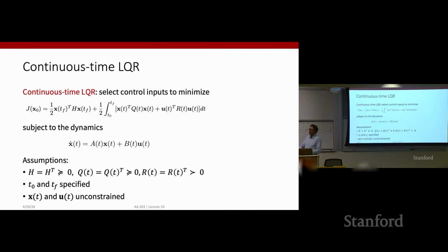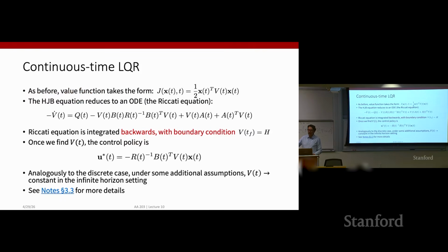So, can you solve LQR by using the Hamilton-Jacobi-Bellman equation? Yes, you can. I'm not going to do the full derivation. It's not particularly insightful. For those of you that are interested, the way that it would work is as follows. We know from the discrete time formulation of LQR that the optimal cost to go is quadratic in the state. So you start with an ansatz.